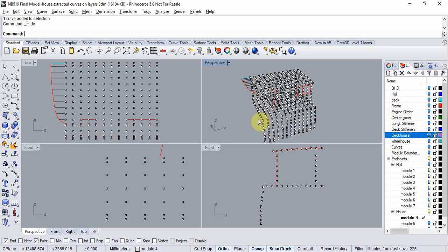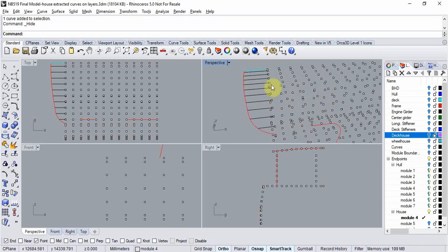First thing we can start with is building this overhang. If we were to build these as single quads, they would be a good bit longer than the existing mesh in the Maestro model. So we'll cut this in half. Actually, we'll use this endpoint and simply cut a section through the remaining curves to generate some additional points to use. We'll also need points defining the end of the overhang.